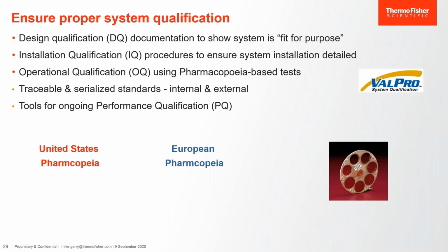Our validation package includes full installation qualification tests. Our operational qualification tests are based on pharmacopoeias, whether it's USP, EP, Japanese pharmacopoeia, or Chinese pharmacopoeia. We use traceable and serialized standards to run these tests, which are again mentioned in these pharmacopoeias. And we provide tools for ongoing performance qualification of the system, which can be routinely done by the operators working with those systems.